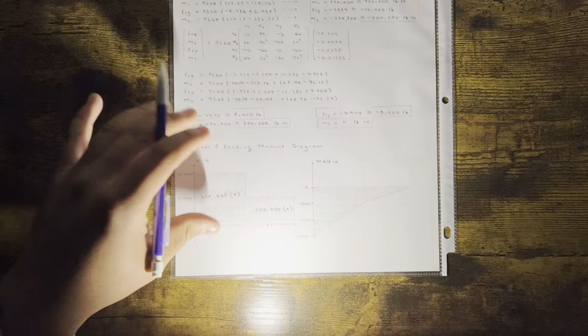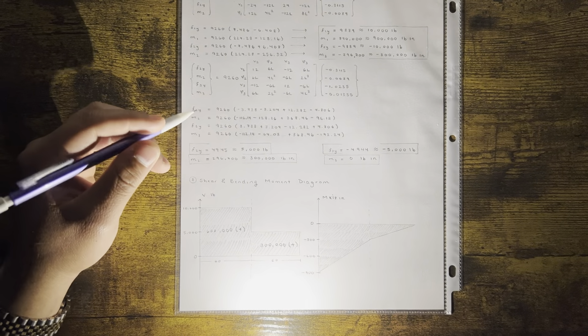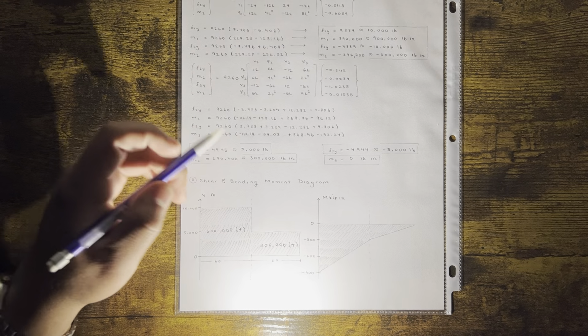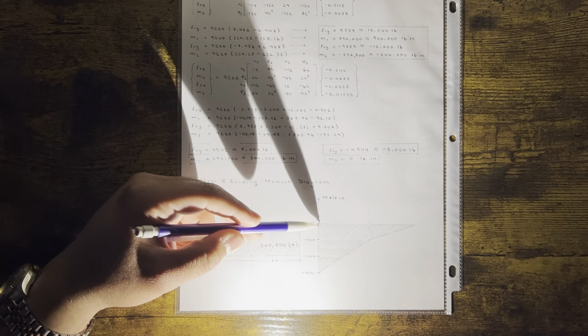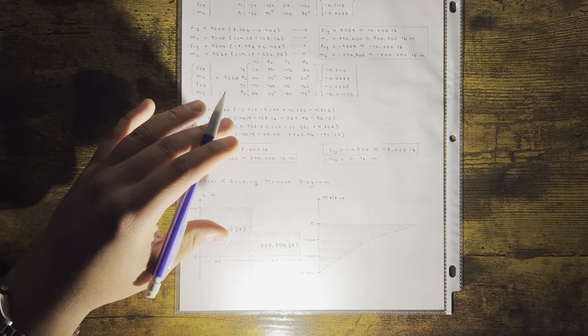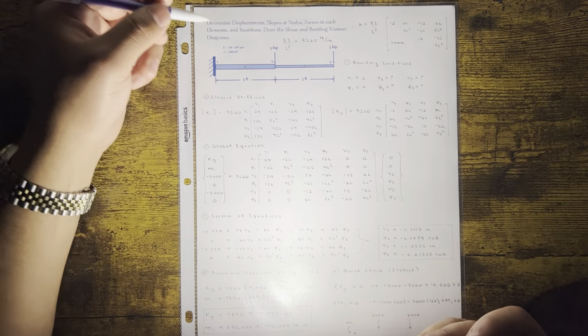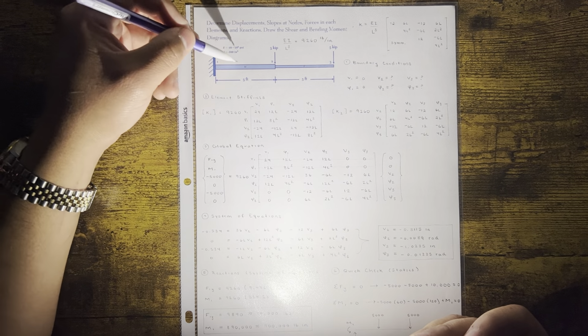If you're ever working as a structural engineer, this is important because knowing this, now you know what your demand is for moment, for shear. They're going to tell you, we have this setup where we have 2 beams, and one has twice the moment of inertia as the other one.